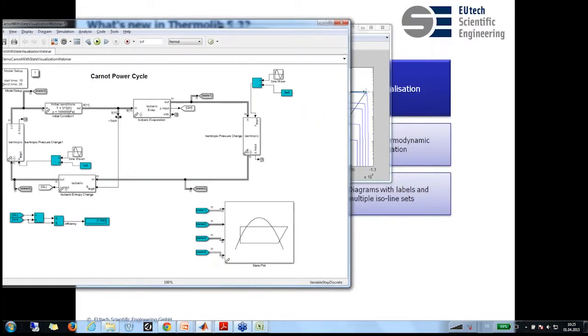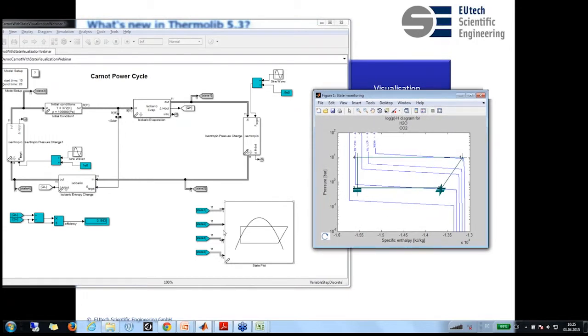Otherwise you would have to select the temperature separately, the enthalpy separately. Of course you can do it by yourself. The advantage is that you have this background image of the isothermal lines, in this case what we see right now, so that you can select certain temperatures where maybe this is your desired operating range and you want to stay inside of these bounds, for example. And you have the possibility to use, like here, the logarithm of the pressure instead of just the pressure by itself. So the standard diagram which you would use for the thermodynamic analysis. And yeah, that's the main advantage.